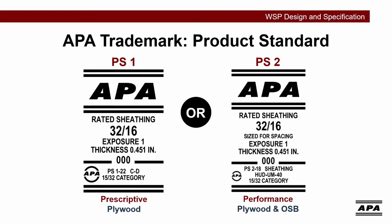Here are 2 examples of APA trademark stamps. The first, on the left, is an example with the PS1 standard specified. This standard is used with plywood structural panels. The second, on the right, is an example of the PS2 standard, which can be used for both plywood and OSB structural panels.